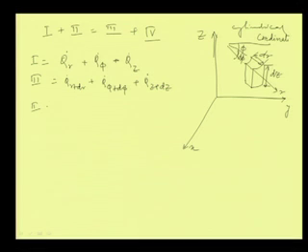So, we will say that this is q dot generation into the volume element, and the volume element will be dr dz and r d phi. R d phi is the small section, this one is r d phi, into dr into dz. So, that becomes the volume of the volume element.